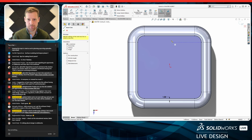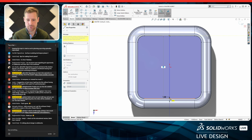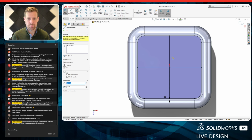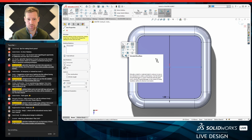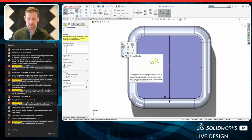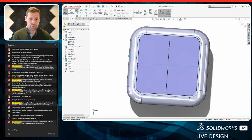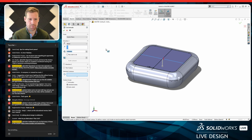I'll use my S key, grab the line tool. You can also use the L key just to bring up the line tool. That's another quick tip for you. And we can drop a couple of lines on here. Now, I gave you that tip before: don't worry about exiting your dimension tool or your line tool. Don't worry about coming to the confirmation corner to hit check. You can go straight to the Features tab and go to your feature. However, I use Extrude and Cut a lot, so why not add those to my shortcut toolbar? That way I don't have to do all this mouse cursor moving all over the screen. So here I have Extrude and I have Extruded Cut, and I just use them from here. It's really simple that way.